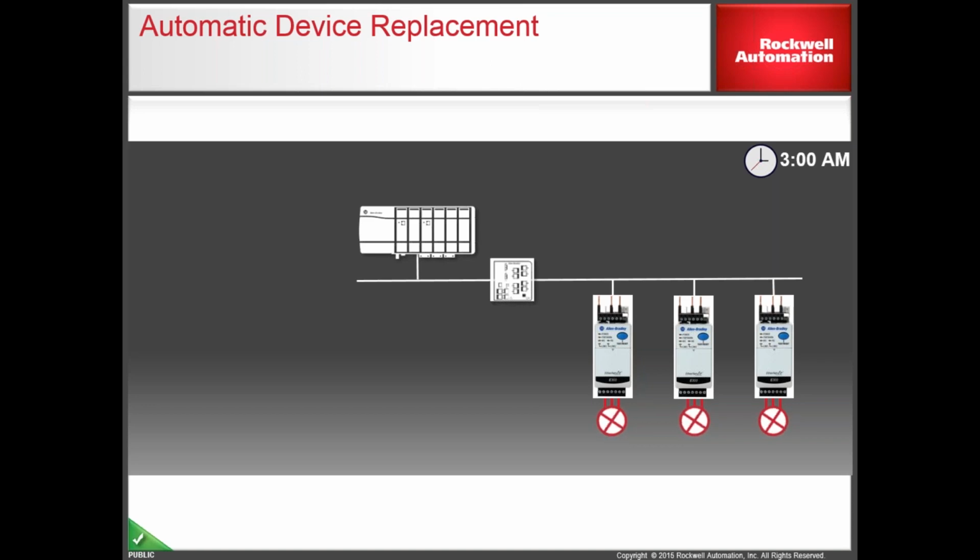There are ways to send a message instruction to the overload, but we run into problems with the Logix processor retaining that configuration. Anytime you make a change that the processor doesn't know about, it's going to constantly send its data back to the device, overriding all the changes. So you could inhibit the module, go to the web page we showed earlier, and change the motor control operating mode. But as soon as you uninhibit that module, it's going to override it right away. Yep.